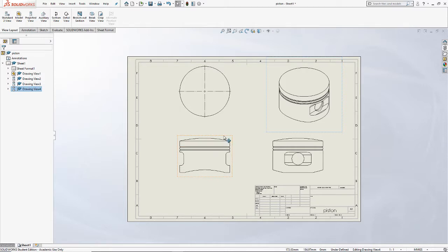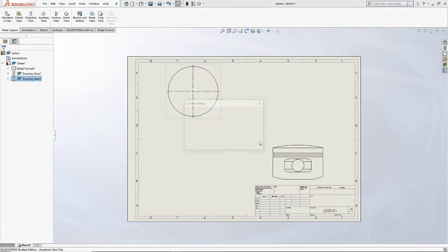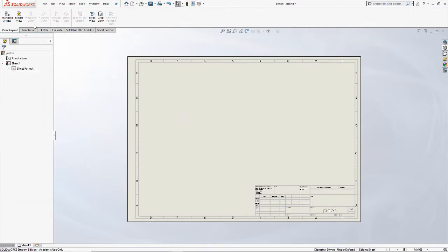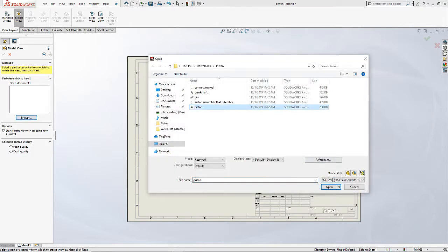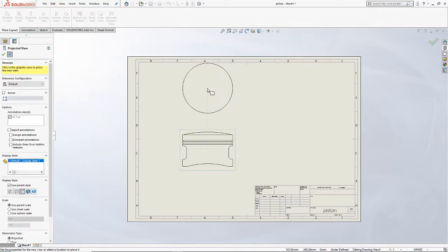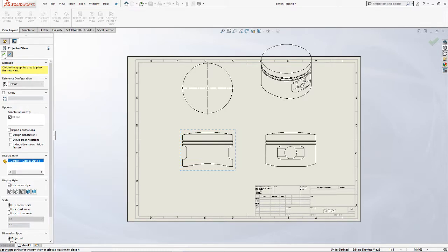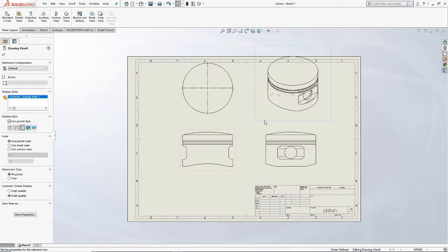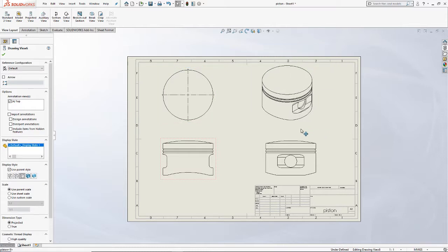So we've created a view of a part. Again, if you missed that, what I did was I went into a SolidWorks drawing and I went up and inserted a part using a model view and clicked on piston, clicked once to define my initial base view, and then from that, my subsequent clicks define additional projections. So in some cases, you might only need 2 views. In some cases, you might need 3. Personally, I like the front view, the side view, the top view, and the isometric view. These are the views that you should be used to from doing the homework assignments.